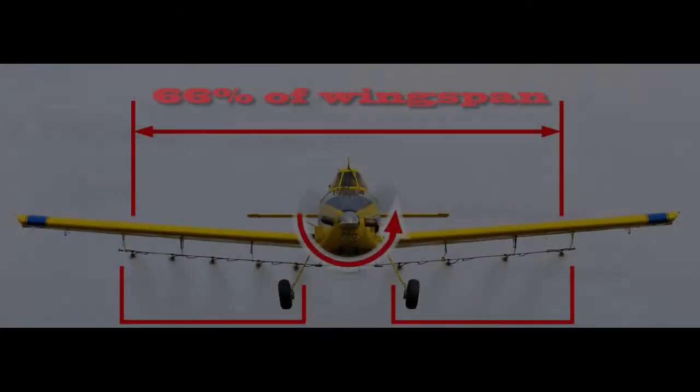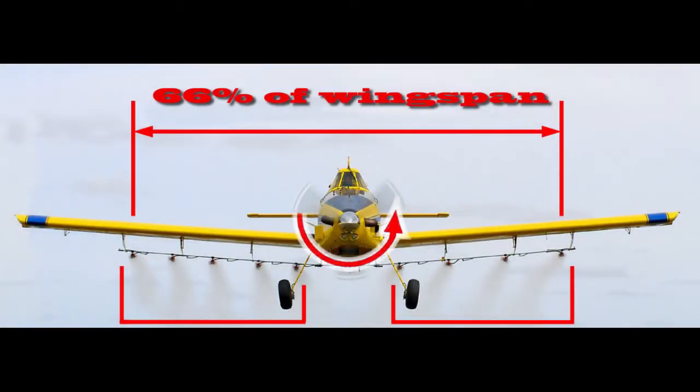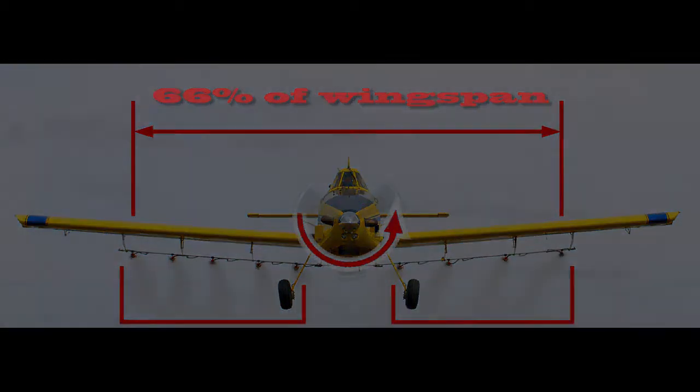The initial starting point should be about 2/3 of the total wingspan. Not the distance from the wing root to the wing tip, but of the total span of the aircraft. It does differ to a certain extent between aircraft, but a good starting point is 2/3 of span.